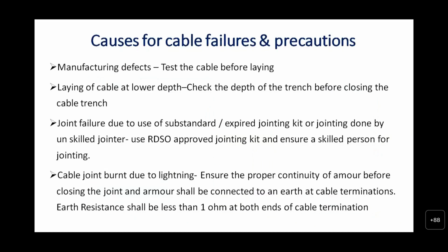So different cable failures and the precautions to be taken are indicated here. Generally, the first one is manufacturing defect. Test the cable always before laying it. Next, laying of cable at lower depth. Check the depth of the trench before closing the cable trench. Joint failures are due to use of substandard or expired jointing kits, or jointing done by an unskilled jointer. Use RDSO approved jointing kits and ensure a skilled person does the jointing.